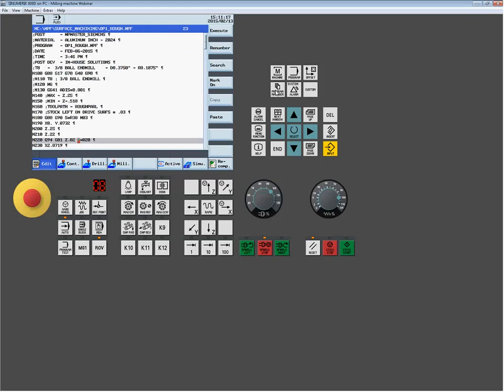Now, a couple of the other modifications I did in turning this into a subprogram: I commented out, I could have deleted, certainly, all tool change commands because I want to do that up in the main. I don't want to have nested tool changes. I commented out any kind of advanced technology cycles, corner rounding, feed forward functionality, anything like that. I don't want that here. I want pure cutter path.